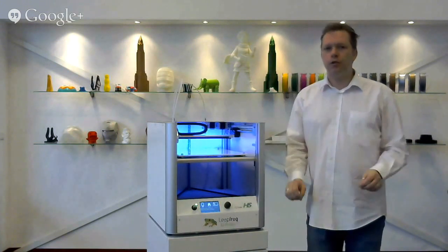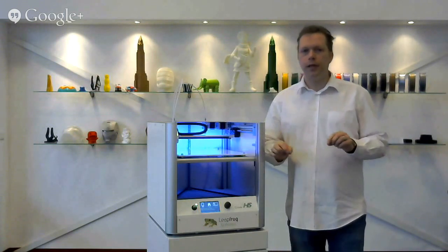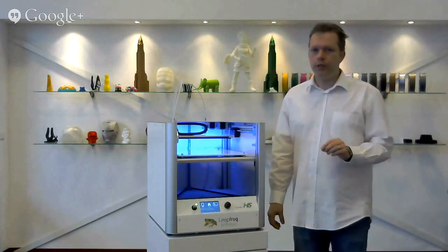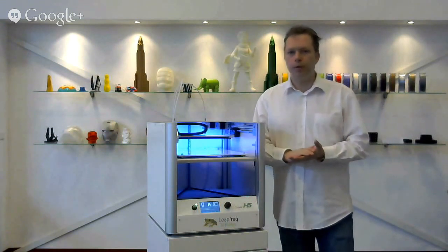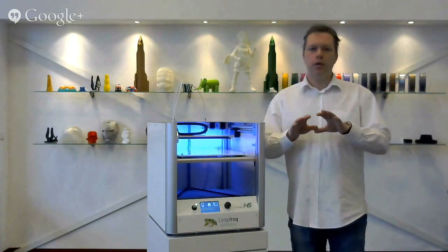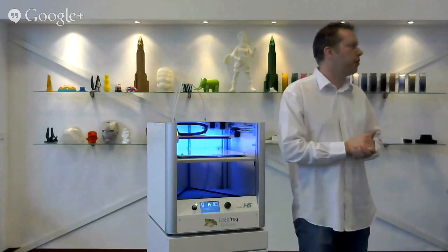The first layer is crucial. When you start 3D printing, always make sure that your first layer is absolutely 100% accurate. As soon as the first layer is not stuck to your bed properly, or it's warping or shifting, or small crumbs are appearing, you can stop printing because it will only get worse and it will drag your print off your bed.